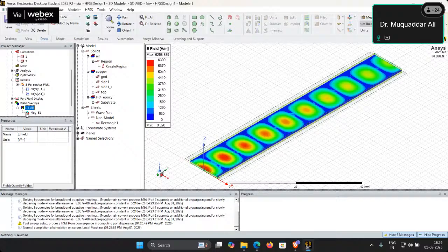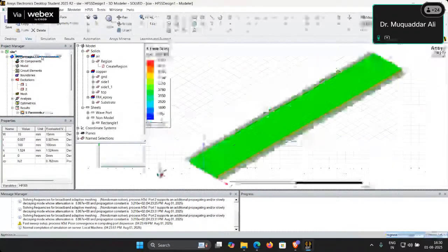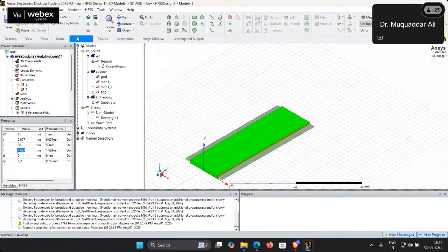Okay. So in a waveguide, or in the dielectric filled waveguide, our field will be confined by the waveguide. So we will not be using this FR4, because from this simulation what we have observed, at least half of the power is being lost. Okay. Now if I decrease the length to 50 mm and try to simulate it again,